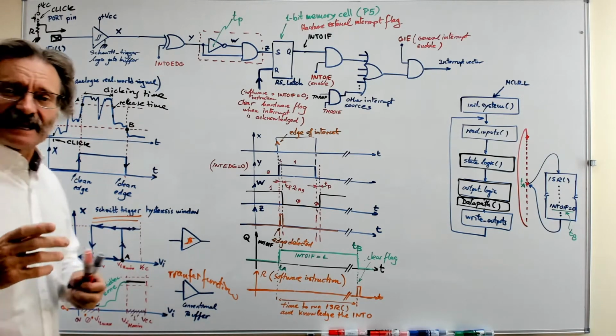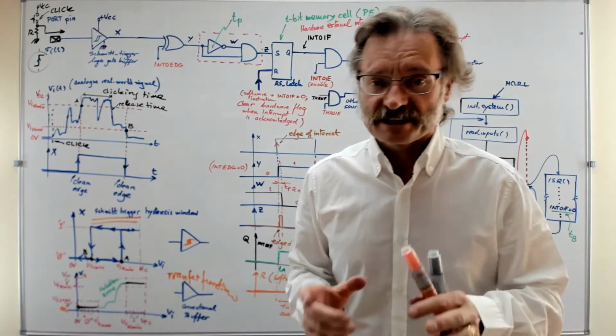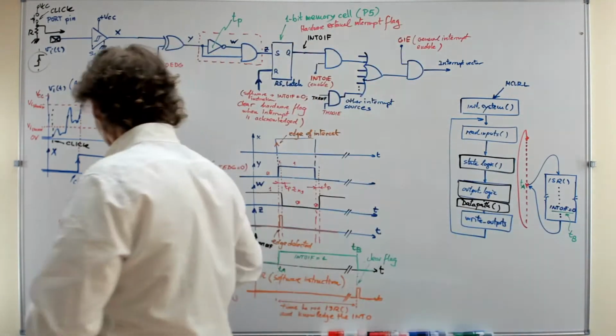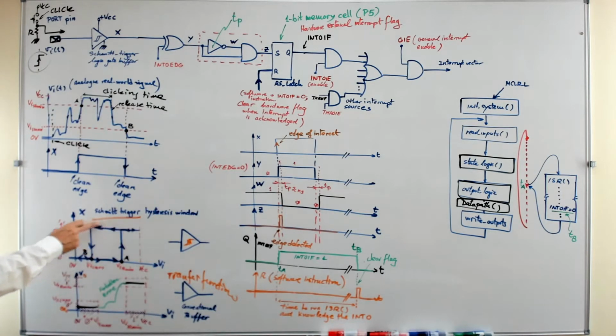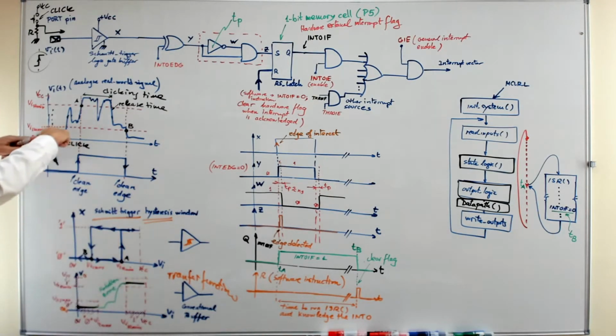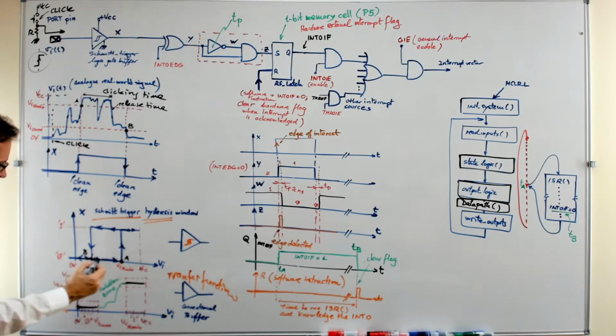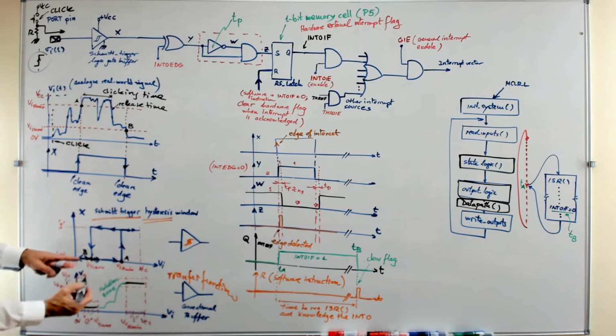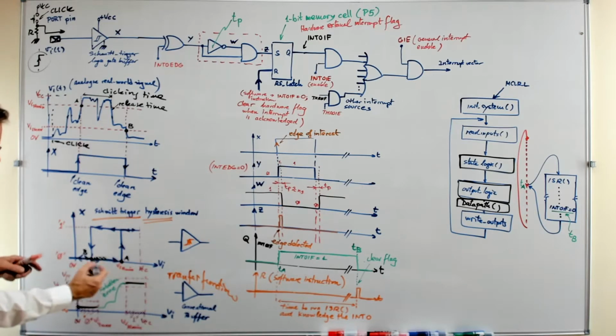comparator. A Schmitt-trigger comparator is a kind of gate that is managed using this kind of window, and this window has a proper name: the hysteresis window. The way it works is like this. You can apply a voltage from 0 to VCC as maximum. If you start at 0 and go up, you can go beyond Vi low maximum and nothing happens. The output is still 0.